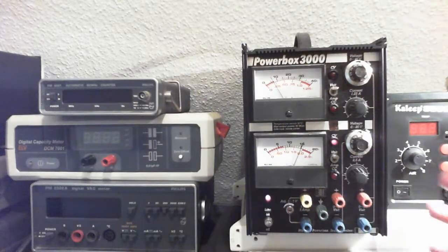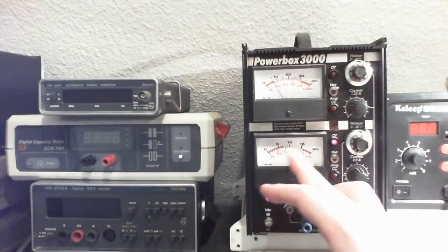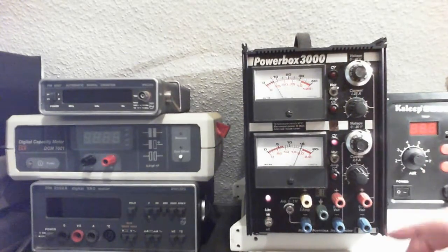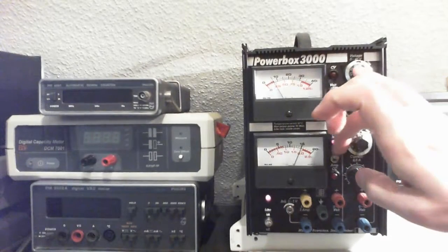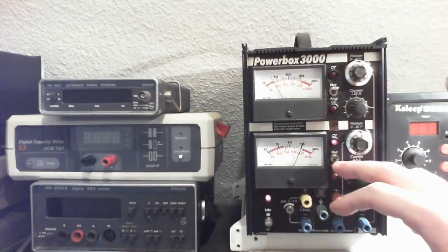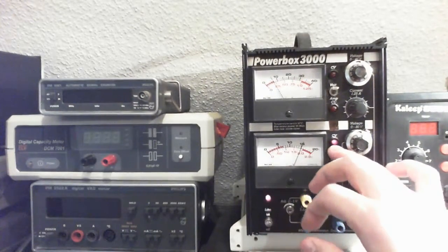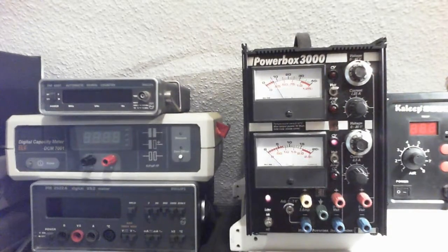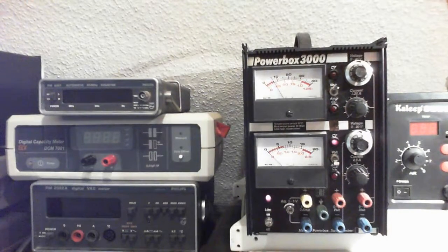And moreover, on this power supply, and on most power supplies that have an analog meter, the analog meter is actually 2 meters in 1 meter, meaning that you can see this switch over here. On the top it's written volt, and on the bottom it's written amp, meaning that if I put this switch in the top position, you're reading voltage over here. If I put it in the bottom position, you're reading 0, meaning 0 ampere. And of course I can connect some sort of load to this power supply, and we can test it.